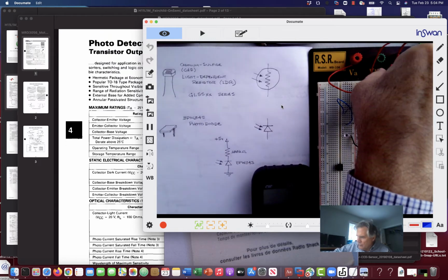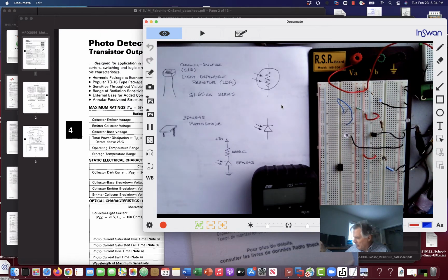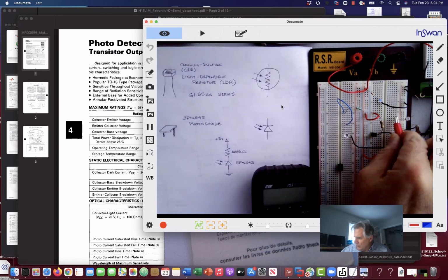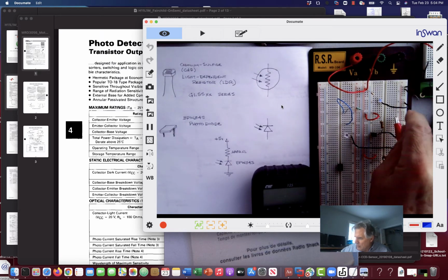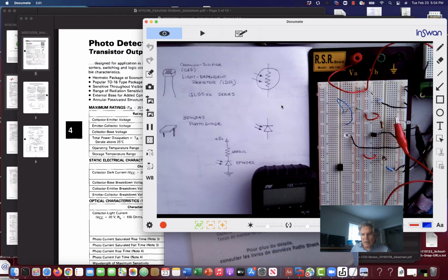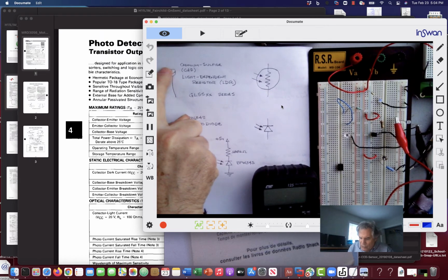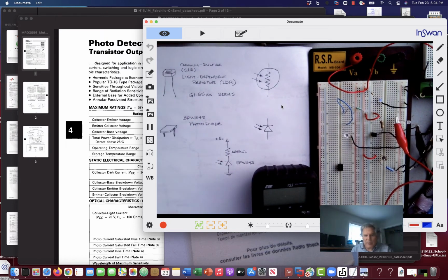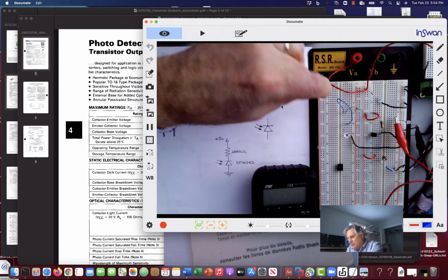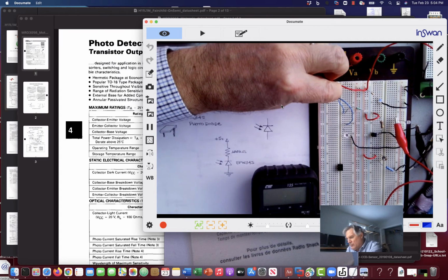The very first device that we will discuss is the venerable, moribund cadmium sulfide light-dependent resistor. And you can see that described here. There's a little substrate here with some sort of serpentine conductive path on it, and that path has cadmium sulfide in it. And the cadmium sulfide is affected by light. Its resistance is affected by light.